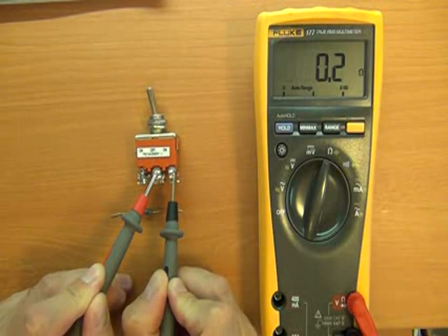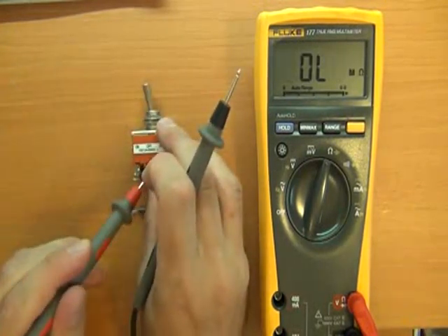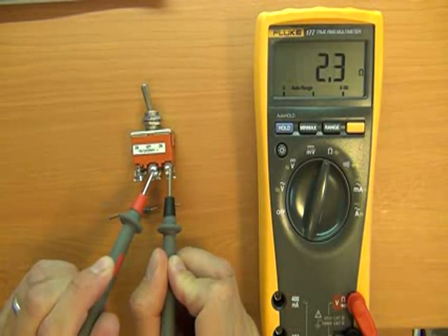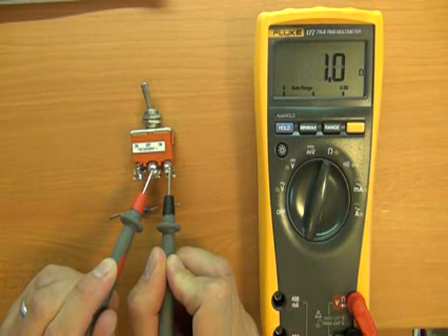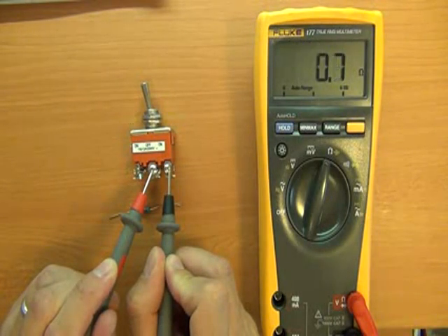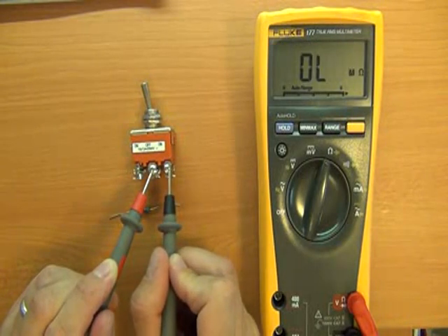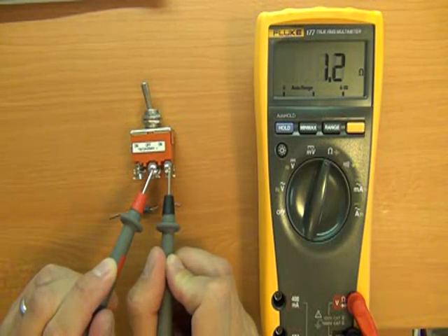So remember, as I said, there was that resistance potentially in the lead. So in essence, we've got close to zero resistance going through here. I say that, and as I play around, you can see we're getting just above 1 ohm. This is also where you can check continuity if you don't have a continuity buzzer: put it to the resistance setting on your multimeter and check resistance. Obviously you want as close to zero as possible to show that you've got good continuity.